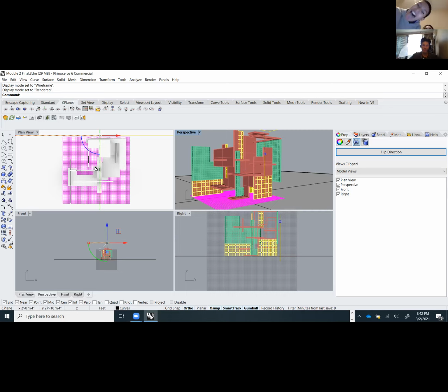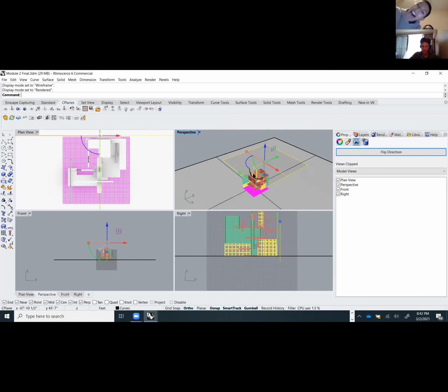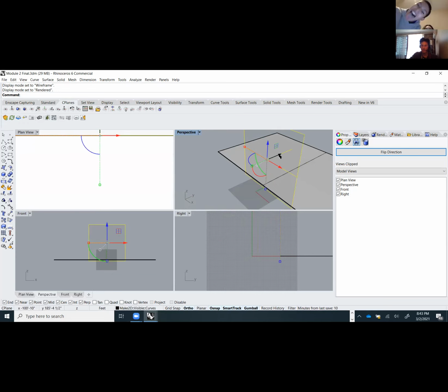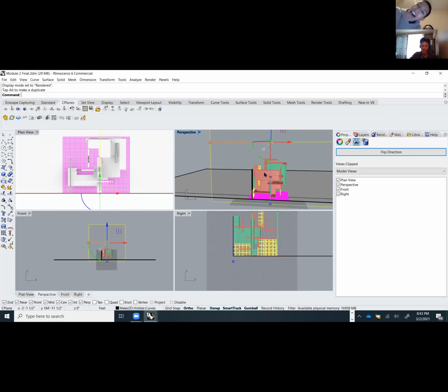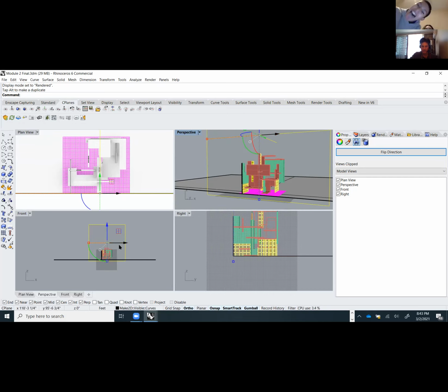So you can cut it vertically, like if I look at my plan view, this way or this way. Let me try. We're going to click on this arc and type 90 degrees. Then I'll move my gumball tool so it reveals my model. I'll take a look at it this way and see what it looks like.